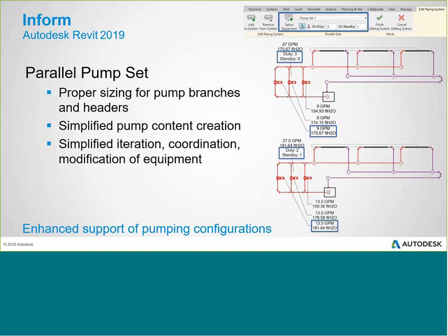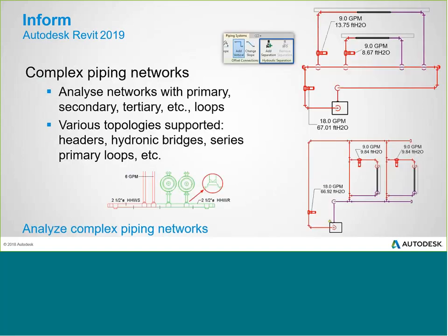Through the new information, the things that they changed in the settings for pump systems and flow direction, those complex piping networks, you don't have to worry about changing the flow rates on things at the end of the system or the beginning of the system. As long as your families are created correctly, this stuff should read independent of the order that you place them into the system. So this is a huge enhancement for calculating things like head loss in plumbing systems. I know those are more discipline specific, but they were pretty big enhancements in terms of creating piping networks.